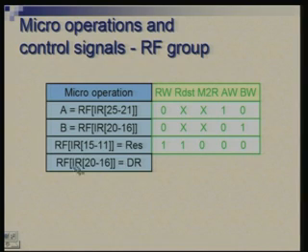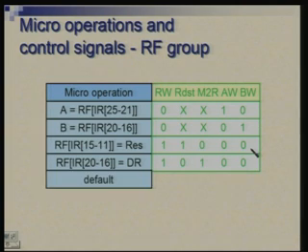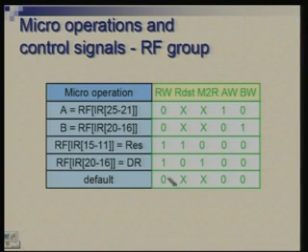This is writing DR into register file. So, again RW is 1, but this has a different value, RDST is different, because the address is coming from different points, and also the values being written are different. AW, BW both are 0, and default is to keep RW 0. So, we do not make any change in the state here. So, all write signals are kept 0.